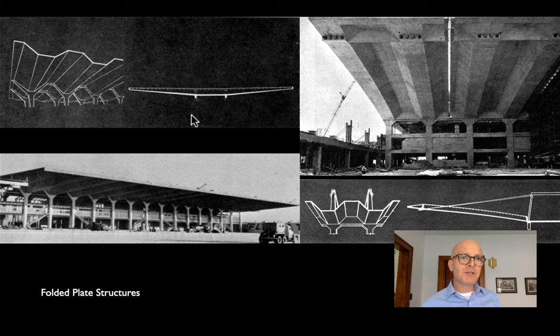And then if you look closely, you can see that we have a beam here at the back, right? Columns supporting this collar beam. And what that collar beam is doing is it's providing the stiffness to the concrete that prevents it from flattening out, and therefore losing its depth, losing its section modulus, losing its ability to span.